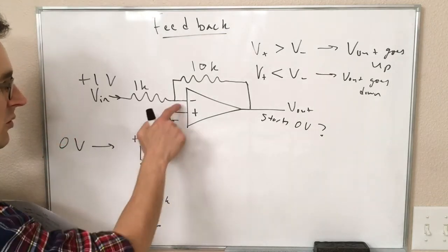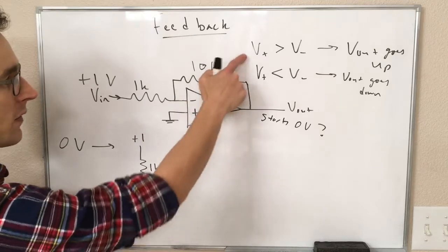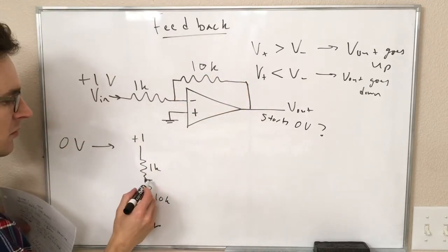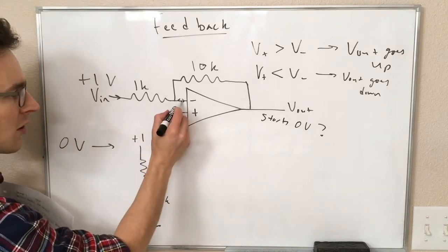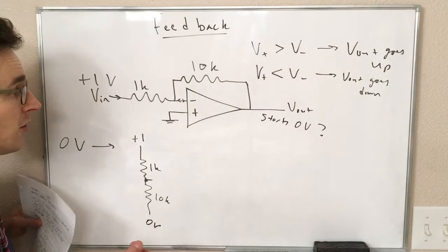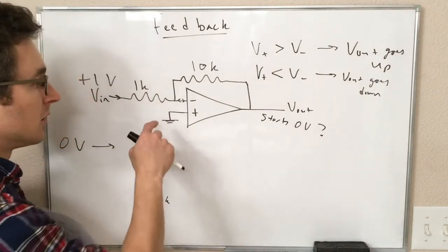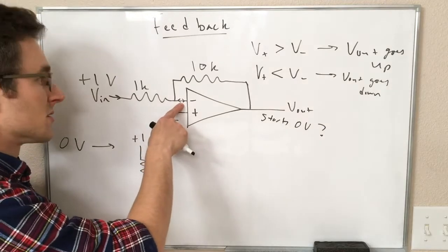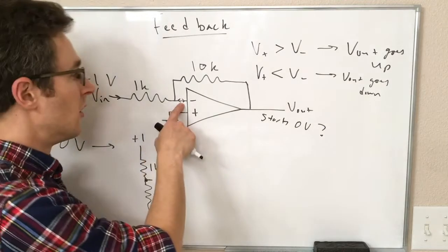One, this is the voltage that we want to find to figure out what the op amp is going to do. And also, it is possible conceptually that there could be a current flowing in or out of the inverting input, but for our op amps, we know that ideally the input impedance is infinite, and even for real op amps, it's 1 million to 1 billion ohms.